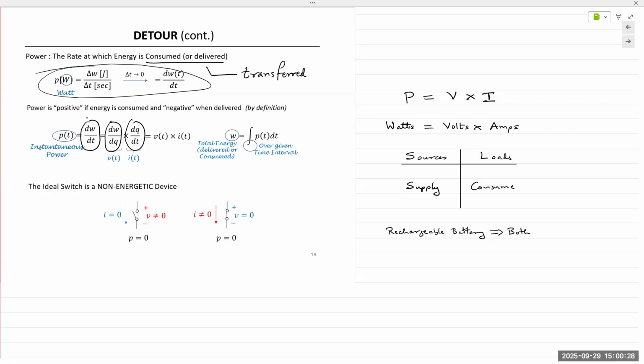When the battery reaches full charge, it has a built-in chip that tells the module, I'm full, I don't need any more. The power supply module controls the charging, and once it's full, it stops the charging. At that point, it goes into bypass mode, meaning the battery is bypassed and the AC power outlet goes directly into the laptop. I had one smartphone very early on, where you could plug in the phone, remove the battery, and the phone would still work because it had bypass mode.